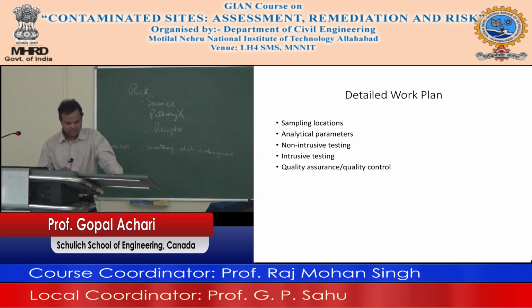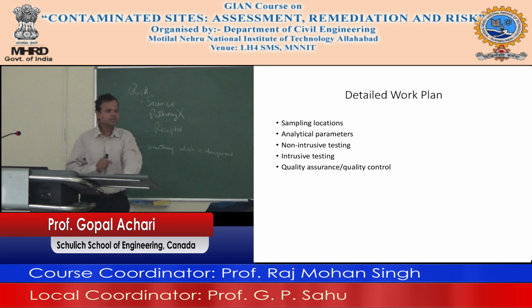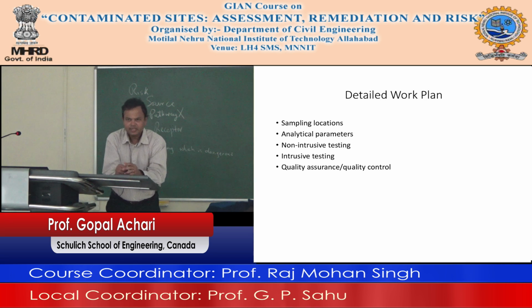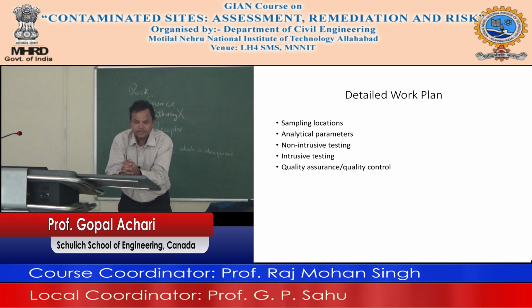Intrusive testing is things like soil sampling, water sampling, QA/QC. This is very important, QA/QC, because anything that you do should be defensible in a court of law. You have to have that level of preciseness, because at the end of the day you will give a report and move on to another project. Somebody might read this report 2 or 3 years from today. The guy might be trying to sell the land, and a different consultant from the other side might be looking at your report and challenging your findings. So you have to be very careful how you do it.